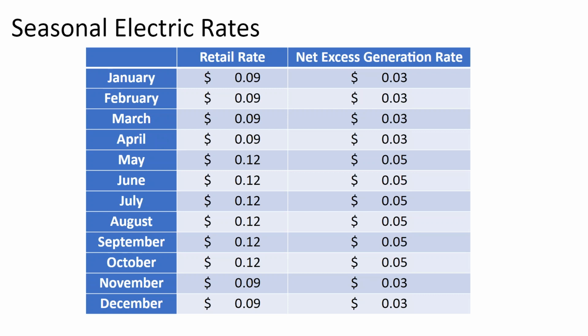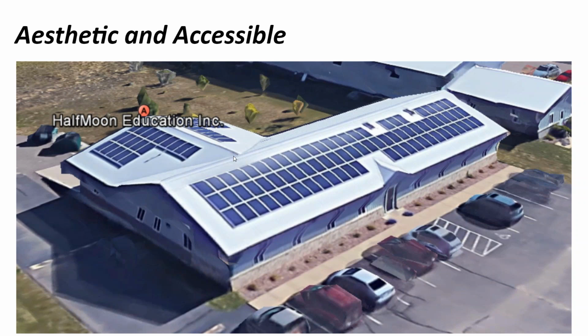How many 60 cell panels would be required for a 2,800 square foot residence with typical power requirements? There are two things you can do for that. One is to just look at the rooftop and determine how many panels you can fit on the roof, and then a good project size. When we did this project, first, this is the best roof surface, so we're going to use that first. Then there were some roof obstructions here and here, but we still had electric bill and we still had budget left over to do the east and the west surface. And if we still had electric bill and budget, maybe we would have looked at the north side of this rooftop. But at that point, we had already hit our project goals on at least one of those items.